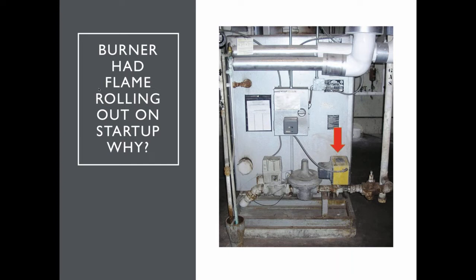And so I started looking at the gas stream. This has been in about 30 years. And if you see the gas stream where the red arrow is, this gas valve was upstream of the gas pressure regulator. So when this valve was shut off, the gas pressure regulator is set for a certain pressure, and it's like, wow, I need this pressure. So it opened wide open. So as soon as the main gas valves opened, this thing was at full open, and then it took a little bit of time for it to come back. But this is something that you see on jobs.